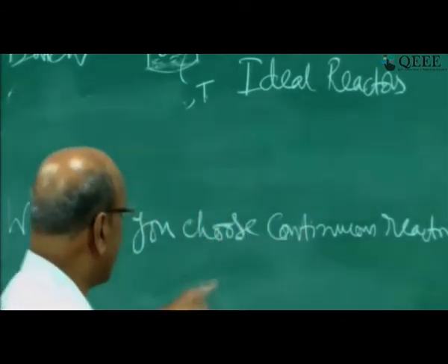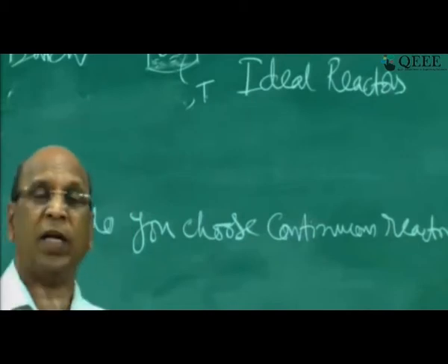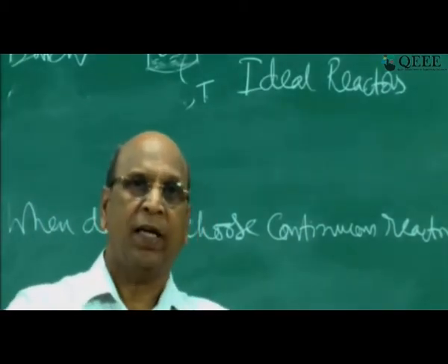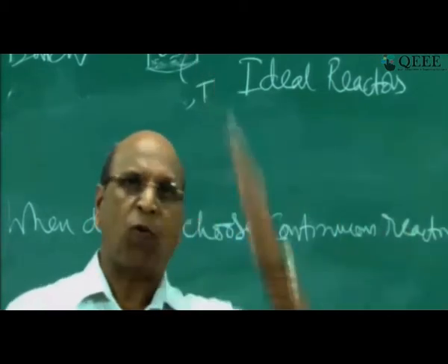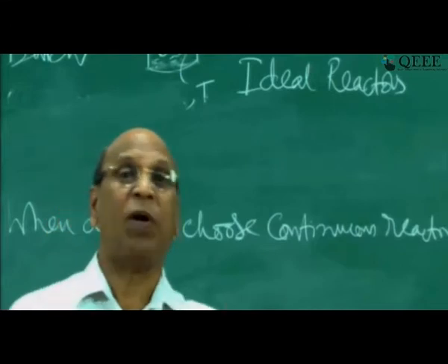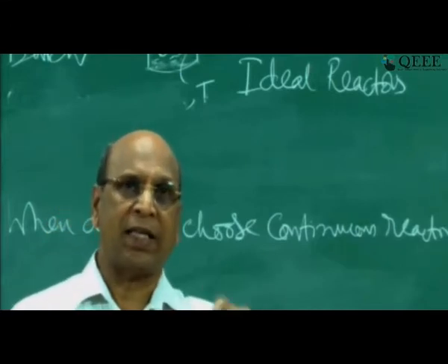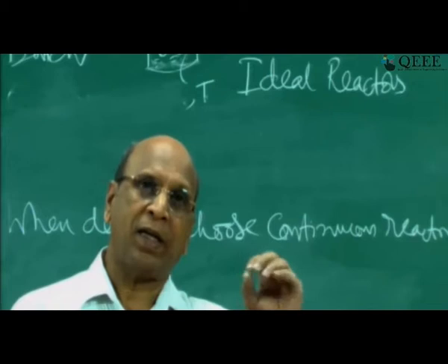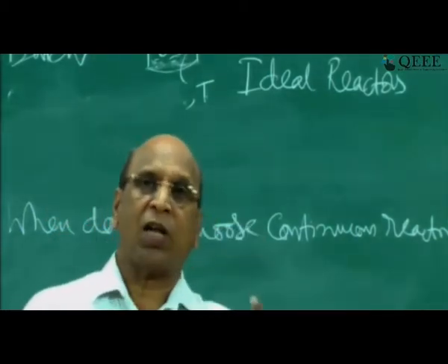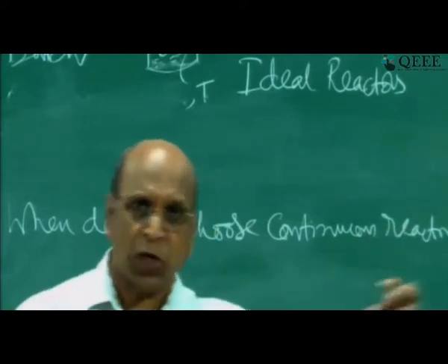But you get very high quality product in a continuous reactor. That means you can always maintain that quality all the time. You may operate for 1 year, 2 years, but quality will not change. But what is the disadvantage? The disadvantage is that the initial investment is very high because it needs a lot of instrumentation, because there is continuous flow.